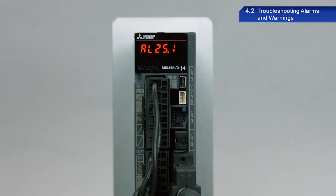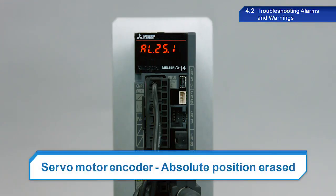The alarm with an alarm code of 25.1 is the servo motor encoder, absolute position erased alarm. This alarm occurs when the battery has reached the end of its service life. Absolute position information will be lost once the battery has reached the end of its service life. Replace the batteries periodically before they completely run out to prevent having to reset absolute positions.